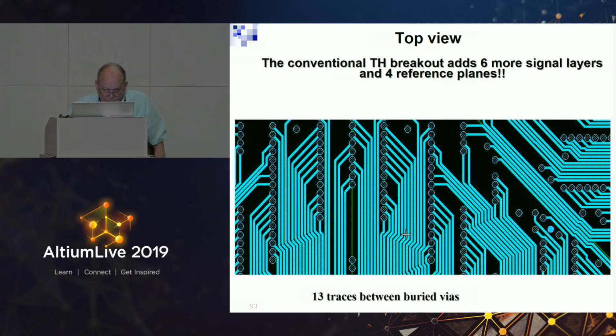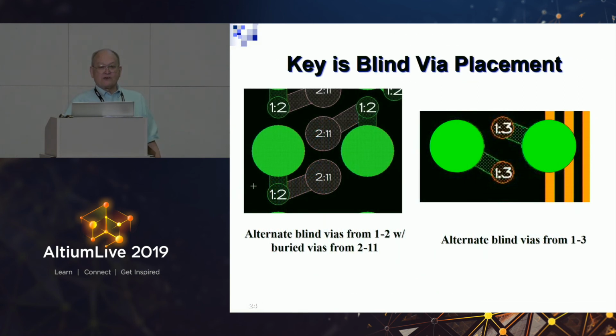Some people ask, why do you have so many? Well, those mechanically drilled holes are now 4 times the pitch of the device you're working with. On a multilayer, the holes are at the same distance as the pitch of the SMT, but here the holes are at a 4 times larger pitch than what you're working with, and that's simply more space. So there it shows you a close-up of where these holes are from 1 to 3, from 1 to 2, and then 2 to 11.